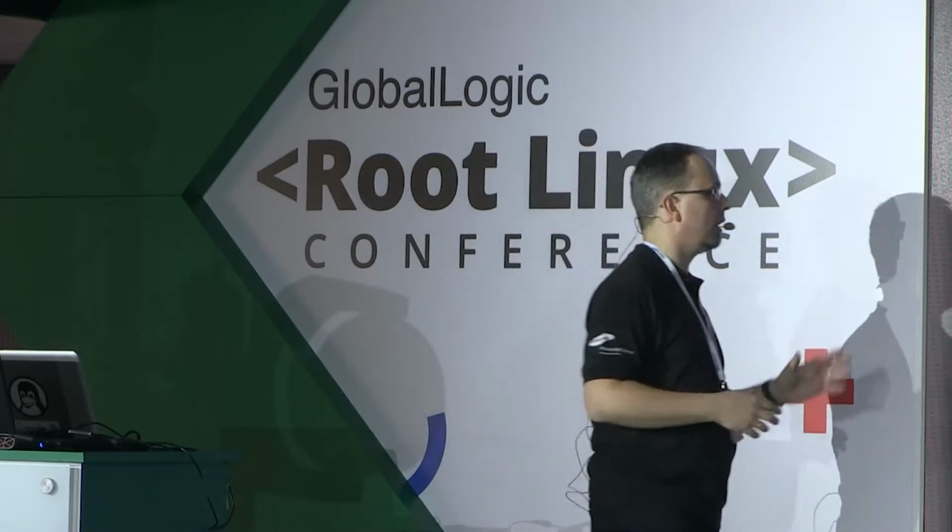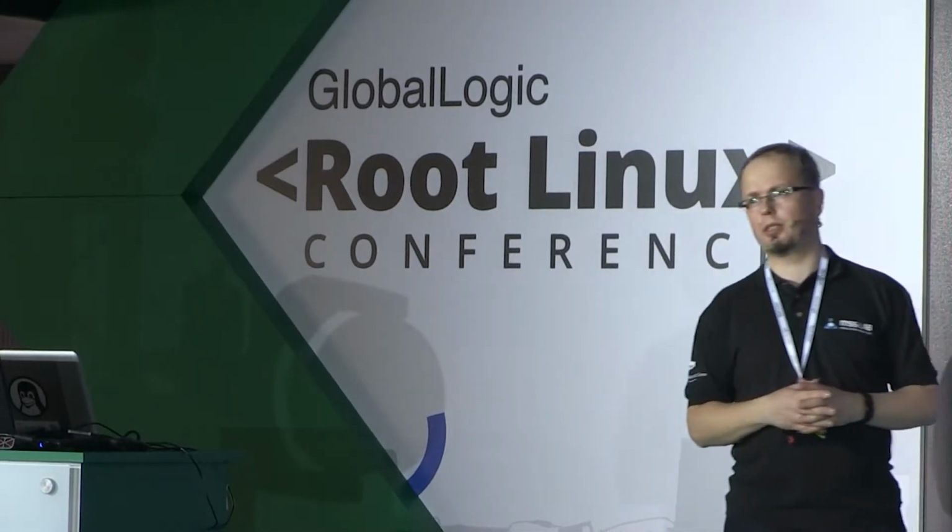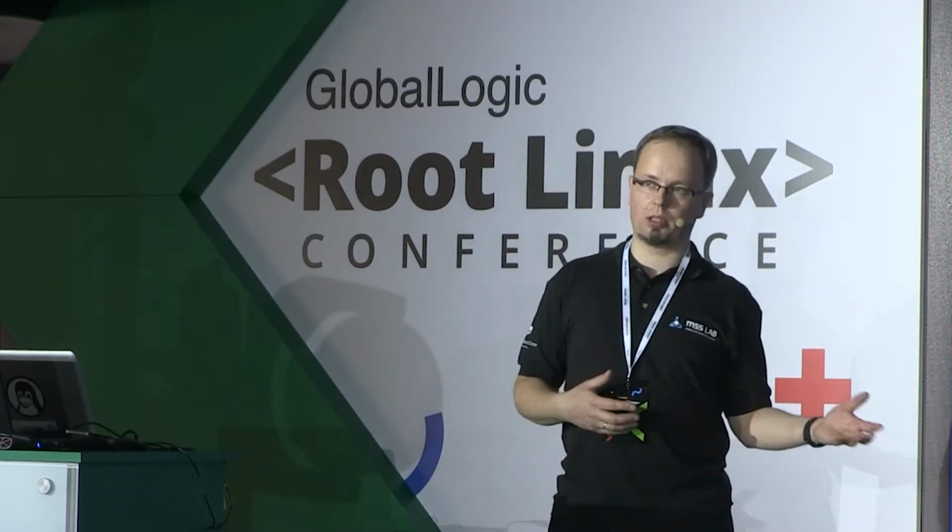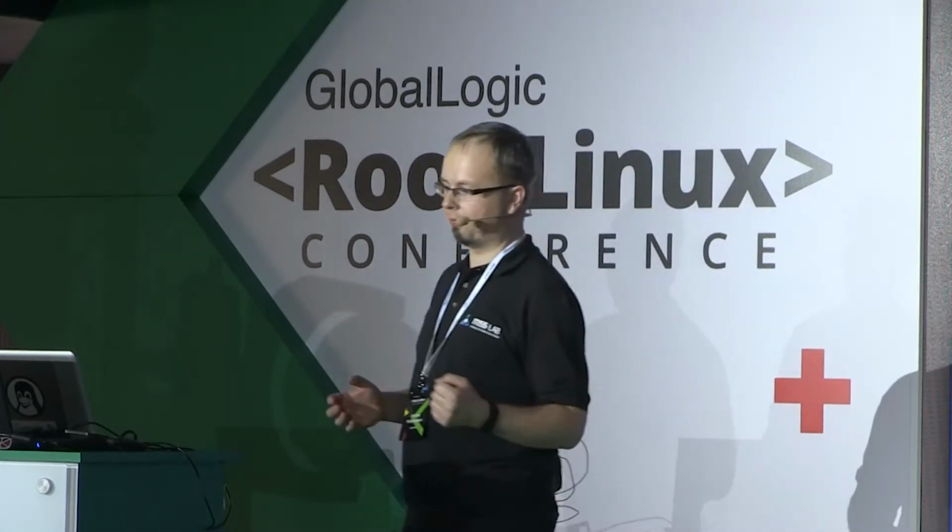Now, the question is what to do if you want your very own function. There are two options. You can write a kernel module implementing it. It's the first option. So you implement your function as a kernel module, you follow the configfs style, and you can use your function as a component of a gadget composed with configfs. It's a valid approach. However, we exchange writing an old-style gadget kernel module for writing a perhaps smaller kernel module implementing our function. So why not use it in user space?